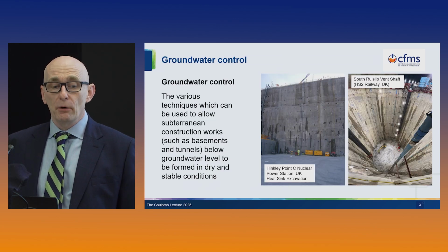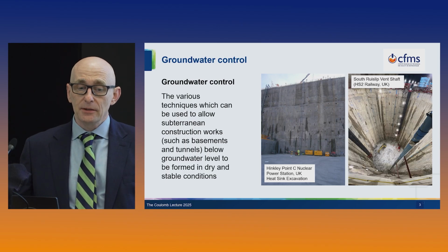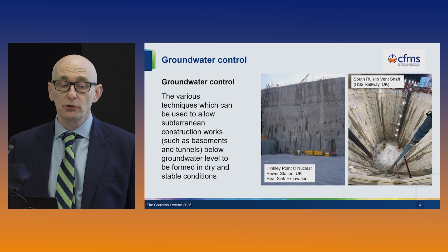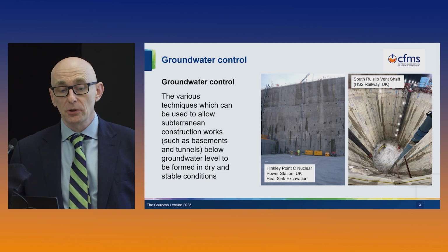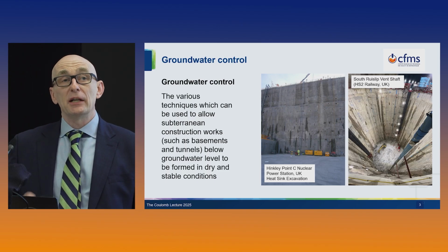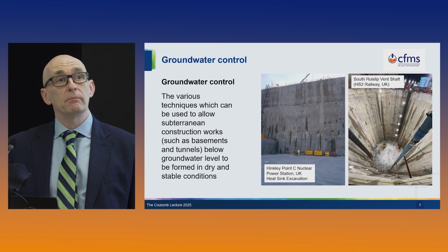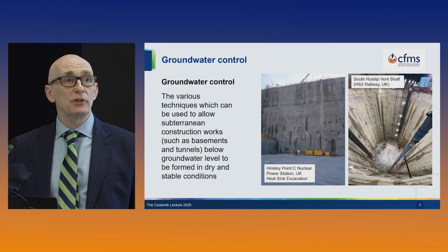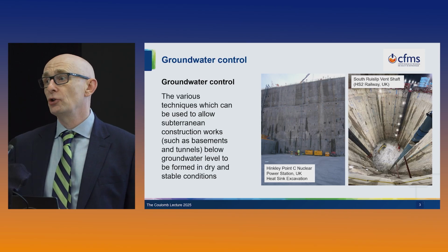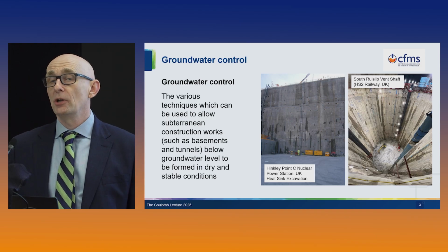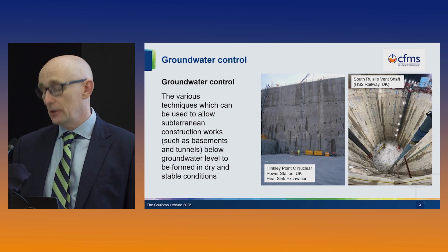I'm going to be talking about groundwater control, and I define that as the various techniques which can be used to allow subterranean construction works, such as basements and tunnels below groundwater level, to be formed in dry and stable conditions. It's relevant to be talking about that in the opening decades of the 21st century because lots of the large infrastructure projects in terms of transportation, energy, water supply and waste disposal involve deep excavations, and groundwater control plays a key part in those.